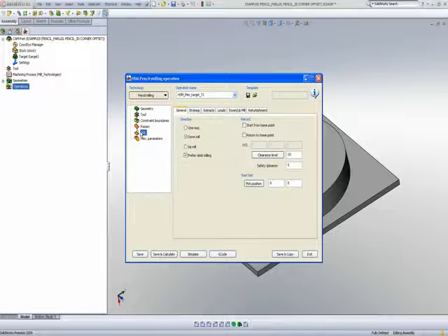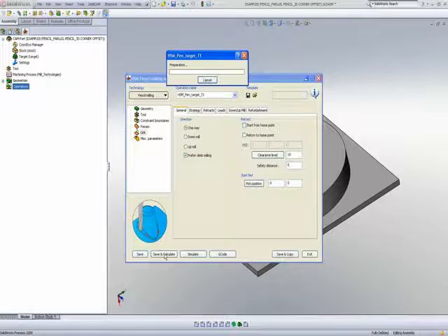And before that, I will go into my links and we'll be working one way, and we'll also prefer climb milling. Now, when I do save and calculate, you'll note that there are certain areas that were not picked up in my pencil milling.